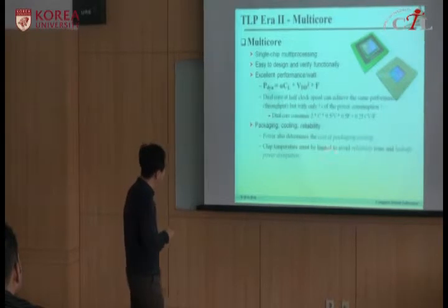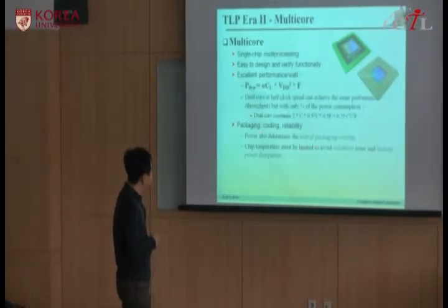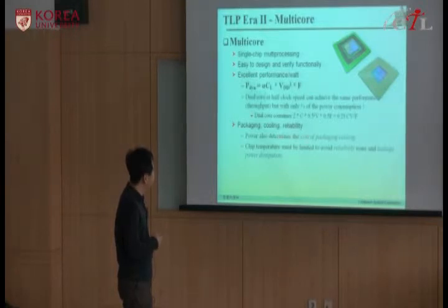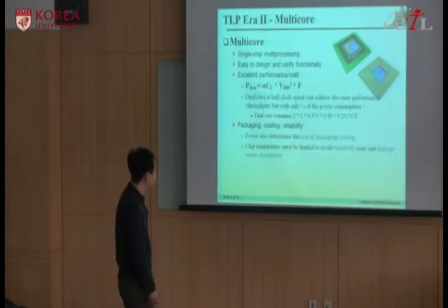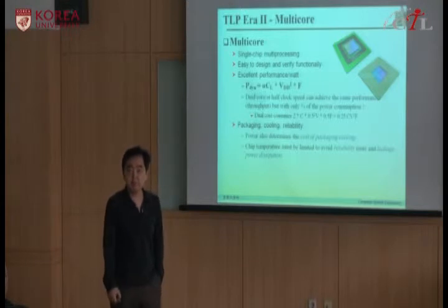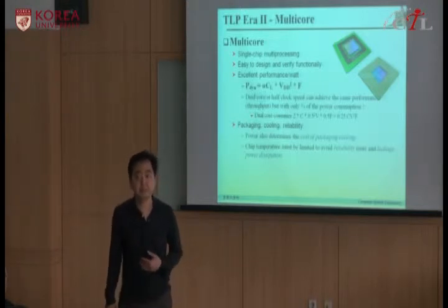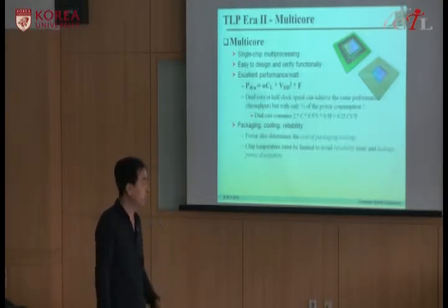and I mentioned here, the other issue was that if you increase the power consumption, if you increase the temperature, packaging and cooling cost increase substantially. Chip temperature must be limited to avoid reliability issues, and leakage power consumption. If you increase temperature, it increases static power consumption also. Leakage power means static power consumption, okay, without switching.